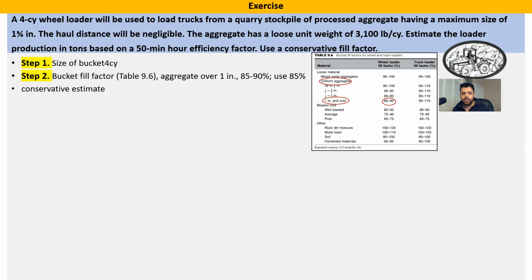Another interesting thing is that you should make a conservative estimate. To have the conservative estimate, you could use the lower range, 85%. So in the exam, just to have a consistent answer, just go with the lower range of the fill factor. So we could have a conservative estimate.